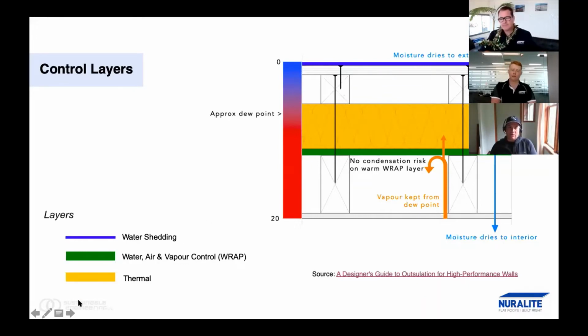So that's kind of the main thing. When you go to these high R value assemblies and roofs, it's really important you control air. That's like the main thing, is make sure you don't have air leaks in that ceiling assembly. If you've got big air leaks, it actually doesn't matter what kind of insulation you've got, you're going to have a problem.